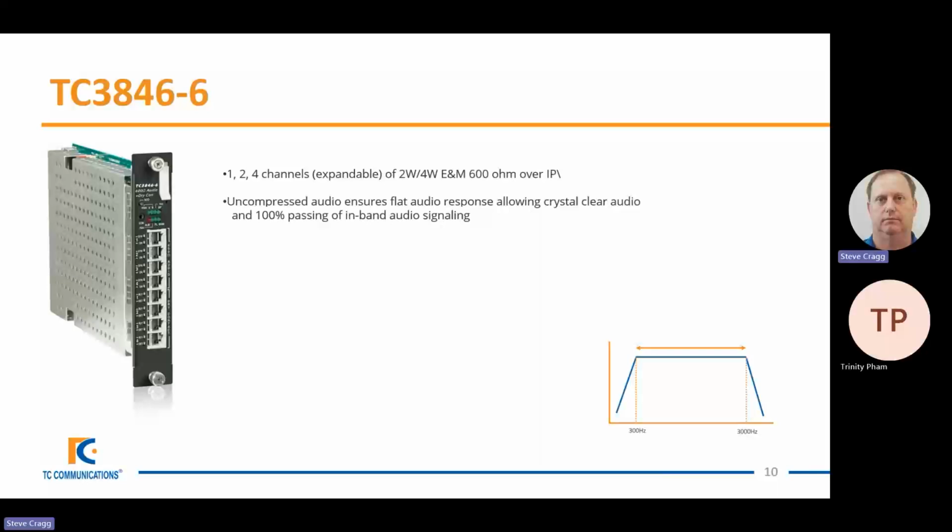your in-band audio signaling. So your guard tones, your key up tones, and so on, all of those will pass through seamlessly. Unlike some that use digitization, they will use a lot of compression that can play havoc with guard tones and so on. Extremely low latency, so ensuring compatibility with your voting and particularly with simulcast systems.